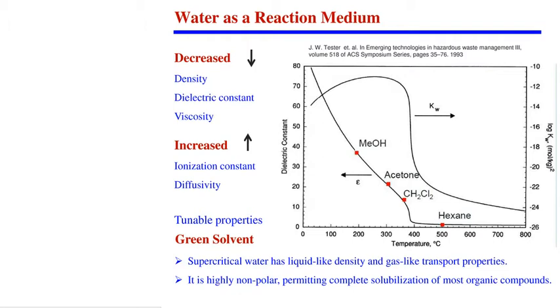Now the liquid you generated contains some of the sugar. What we can do, again, is use this liquid for hydrothermal carbonization, again subcritical water condition, and these sugars can precipitate out as carbon microspheres. These carbon microspheres are basically tarry material, you can see, and they are amorphous, containing 65 to 66% of carbon. That means good energy value, higher heating value, as good as lignin. So they can be used as a fuel.